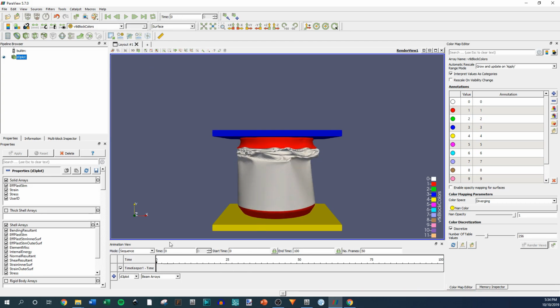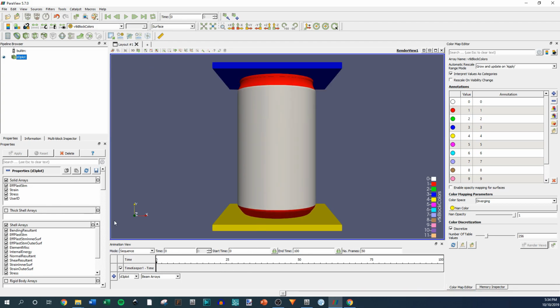So this method that I'm going to show you, if you ray trace, it's going to take a while and a lot of RAM. Just get that out of the way. If you don't have 16 gigabytes of RAM in your computer, you won't be able to do ray tracing, but you can do normal rendering without shadows, and you should be fine with 8. But let's color the stuff in first.